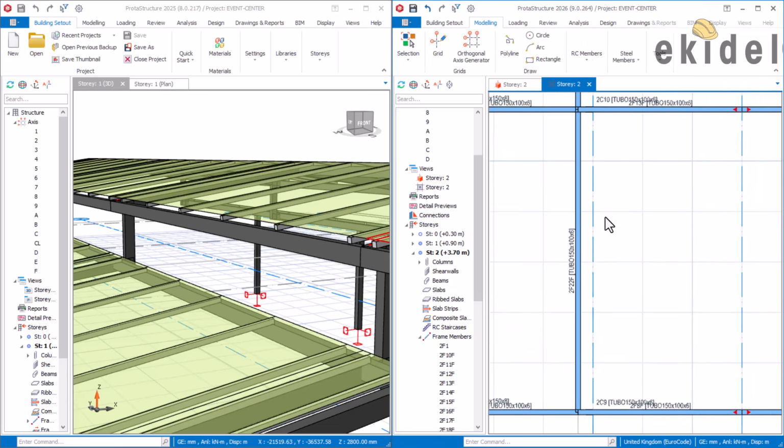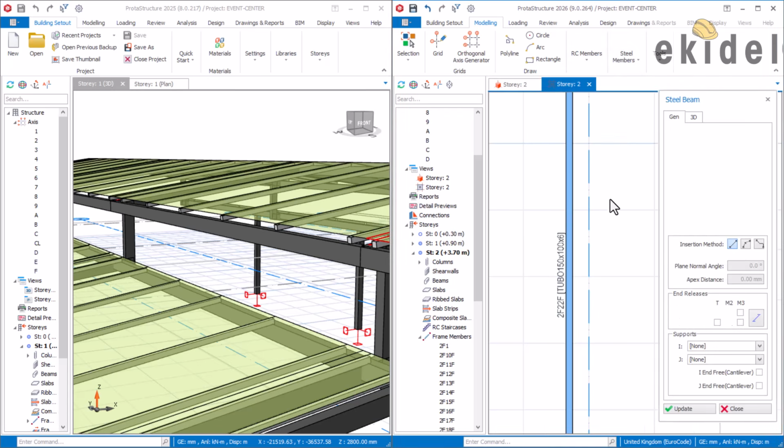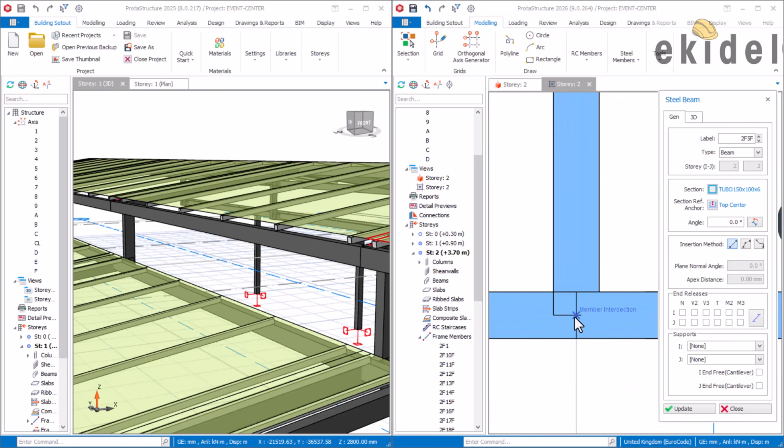Now watch, I will have to come back here again, and then make sure I insert the value. Like before I click, I must see that axis intersection. Now I can see that they will show me, you can see this is a member. I'll say no. I'll be holding my hand. This is no. I say not this one until I see axis, because that gives you the point. Okay. So when I see that, I'll then click.